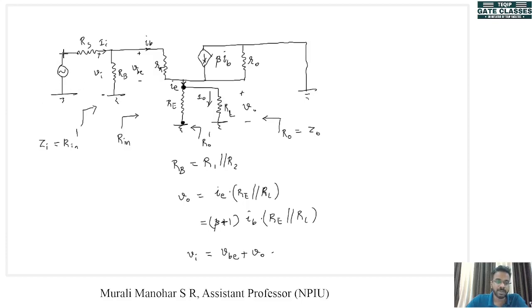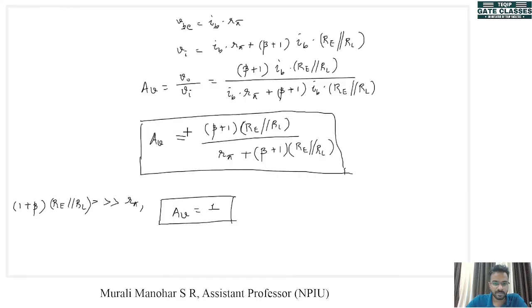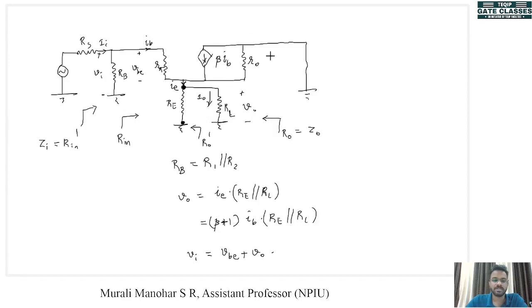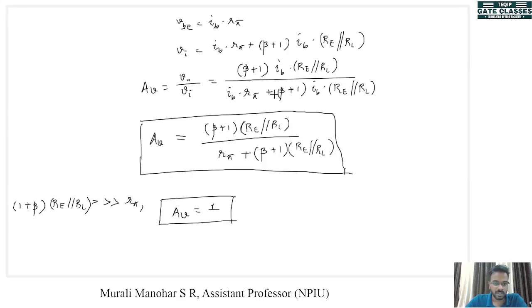So this voltage source will be short circuited. Now there is a parallel resistance combination of Rs and Rb here, then R pi is here. Now there is no resistance here, and we have beta IB here. So we can arrive at a circuit that looks like this. I am also considering that since Ro is a very large value, Ro can be approximated to be equal to infinity. So this will be an open circuit. Okay, so we can arrive at a new circuit that looks like this.